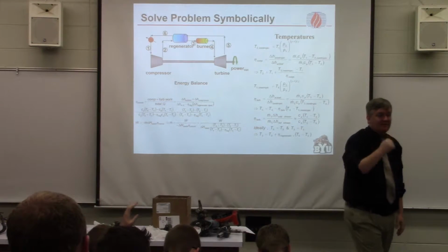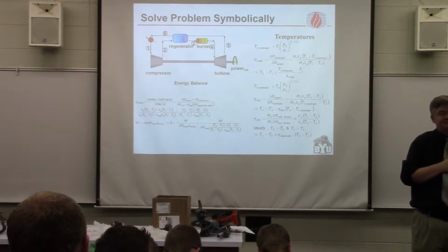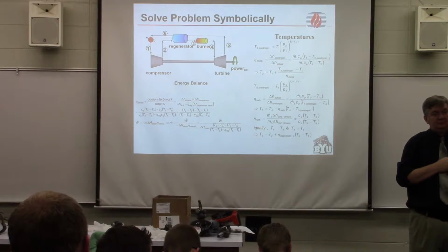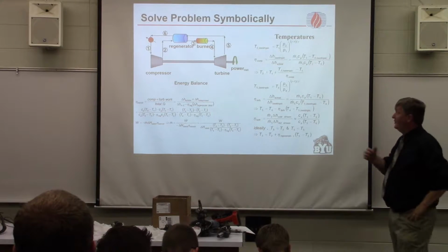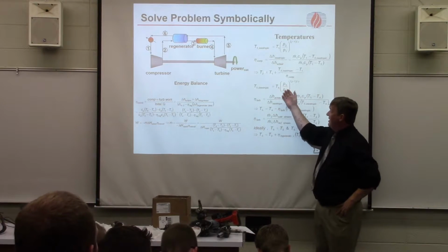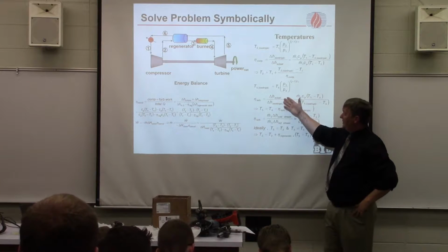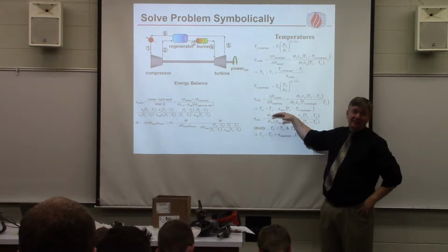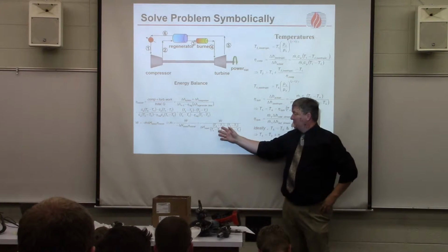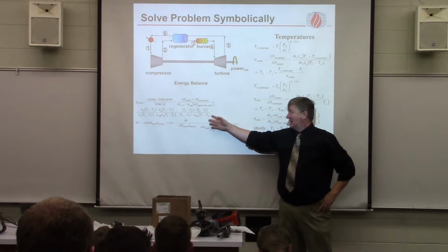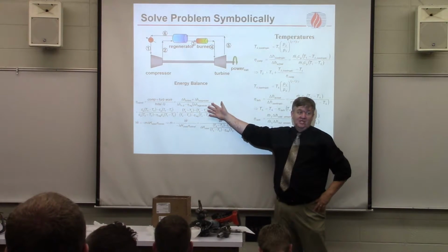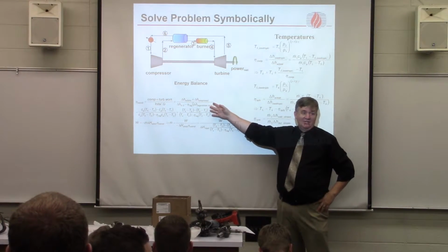Intervals of the heat capacity system. So if we're finding all these temperatures, will that mean we have the efficiencies of like the compression? Right, so if you know the efficiency of the compressor and the efficiency of the turbine and the efficiency of the regenerator, then using this air standard cycle, you can calculate the overall efficiency of this regenerated process.